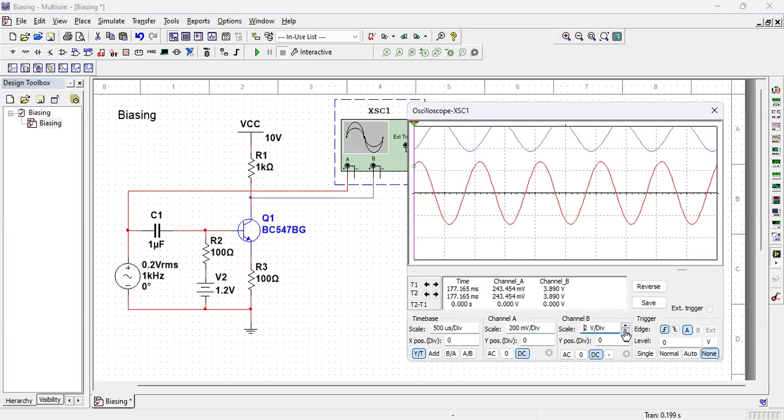But if I increase the output, you see, output here is at 5 volt per division. So it is already, the average is at 5 volt. It is already average at 5 volt, right? Over 5 volt, there is an oscillation. Why? I will explain to you.